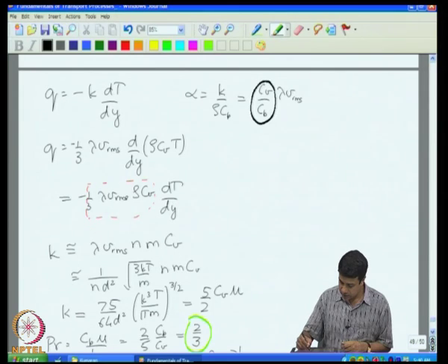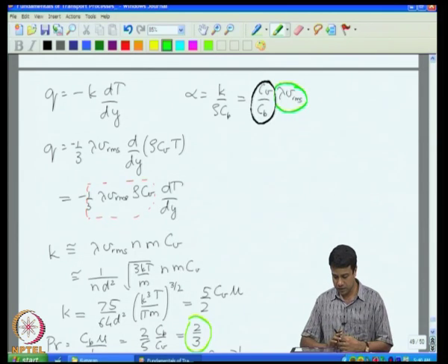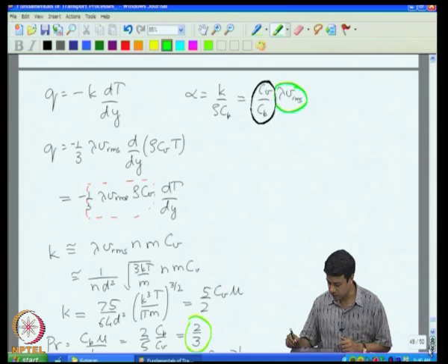This is a dimensionless number, and this thing is the same diffusion coefficient we had earlier for both mass and momentum diffusivity, mean free path times the fluctuating velocity. And it is because of this that for gases the transport mechanisms are the same for mass, momentum and energy, and the diffusivities are also approximately the same. The Schmidt number was 5 by 6, the Prandtl number is 2 by 3 for monatomic gases.